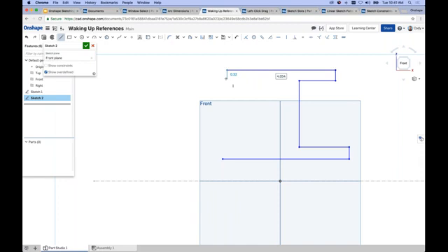And the way you do that is move your cursor over the reference that you want to wake up, in this case, this point. So I move my cursor over that point, and then when I go back, you'll see that point is now a reference that I can add my geometry to. The big thing here is now if I left click, I do not have to come back and add that equal constraint or whatever it is later on, right? And this is going to be very common as you're sketching. So let's do this again.